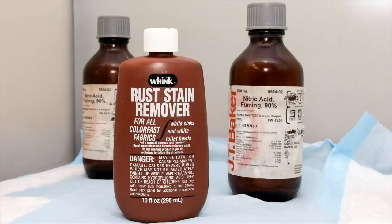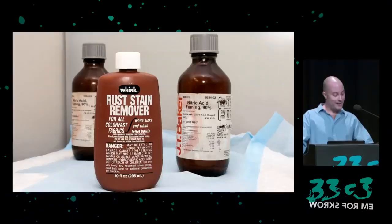I put a small amount of the Wink liquid in a beaker and heat it on the hot plate. Then I drop the decapsulated die in. Using a pipette, I agitate the liquid to disturb the bubbles that form on the surface of the chip so the acid can etch the chip more evenly.